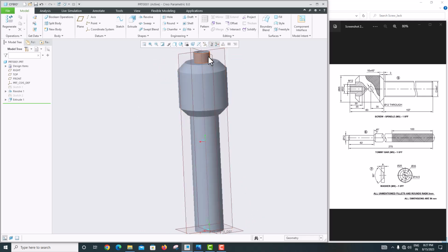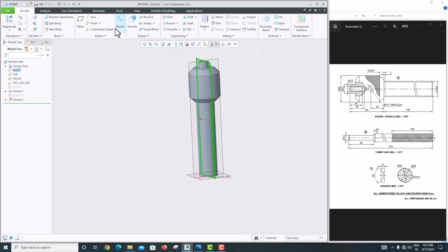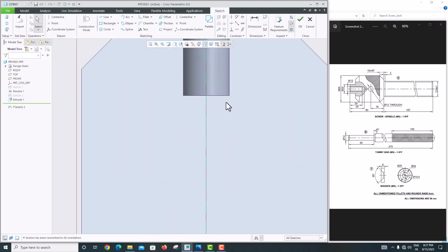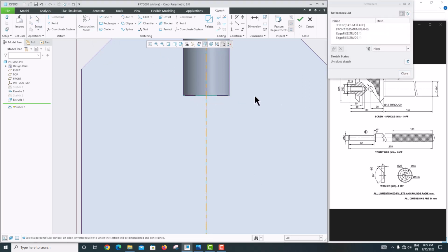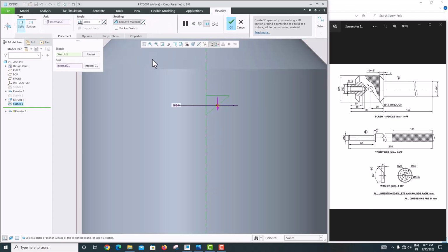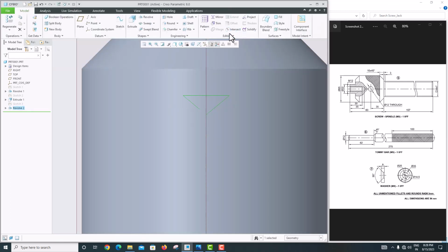And here you can sketch view. Go to cut section. Here you can see like this. Here we just want to make a revolve cut. Just make an axis. Take this reference line, then take a line of triangle. This height has to be 5. Say okay. Go to revolve, material removal 360 degrees. Say okay.